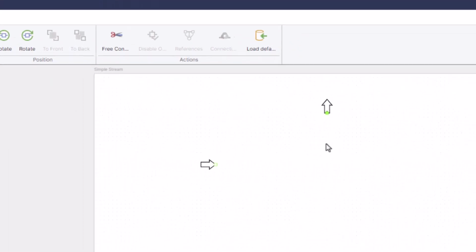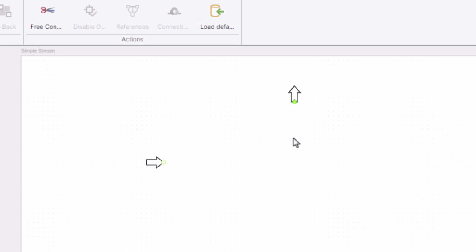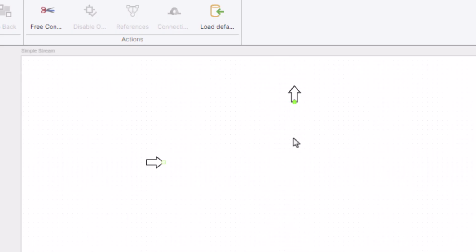The icons in IPSE GO show terminals where you can attach connections. The terminal color reflects the type of the connection. In IPSElib, green terminals are for streams. Connections in IPSE GO always have an orientation. This is reflected by the appearance of the terminal. Terminals for outgoing connections are shown as open boxes while terminals for incoming connections are filled boxes.